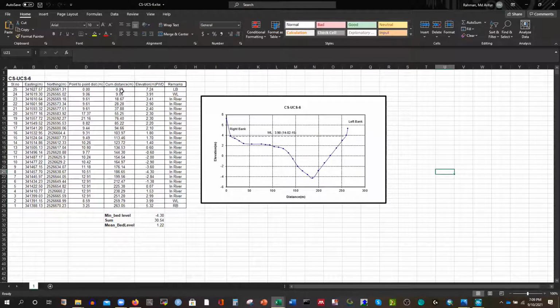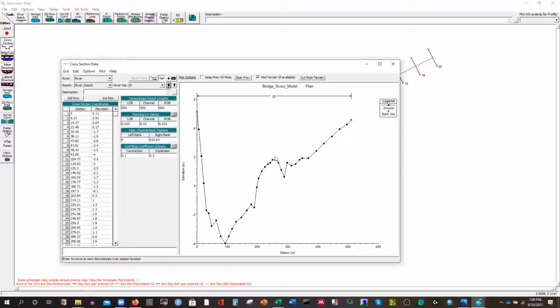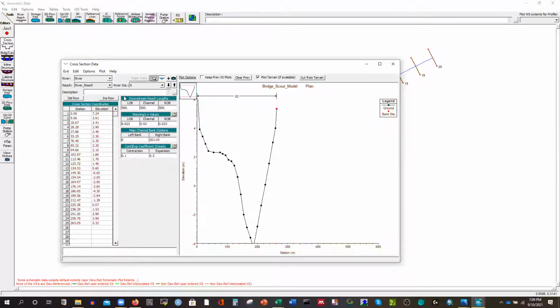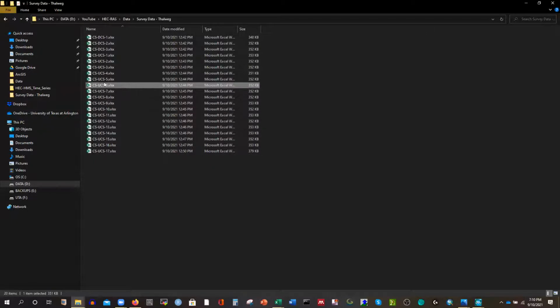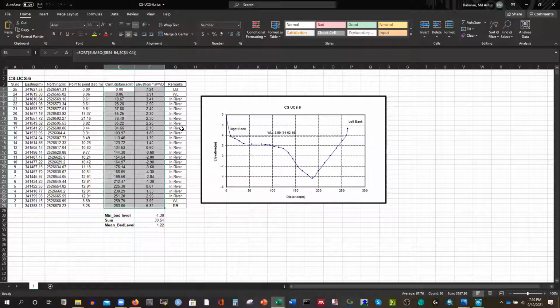So now what we are doing here, we are coming from the most upstream to the bridge location, right? Then we'll cross the bridge and go to the downstream side, and then we'll be done with inserting our cross sections. That's why, when the river width is less, from half a kilometer to 263 meters, we build the bridge there so that the length of the bridge is not that long, only to reduce the cost, right?